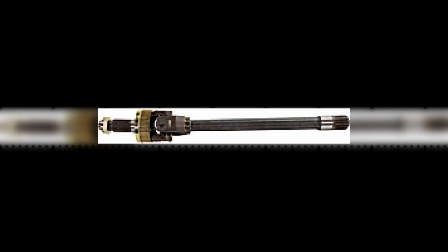Wheel speed sensors play a key role in vehicle safety and stability. Any problems with these sensors can affect the correct operation of the ABS and other safety systems, underlining the importance of regular maintenance and appropriate repairs in the event of malfunction. Code C0040 is specific to a problem with the right front wheel speed sensor. However, other associated codes may also be recorded, depending on the nature of the problem or the interconnected systems.